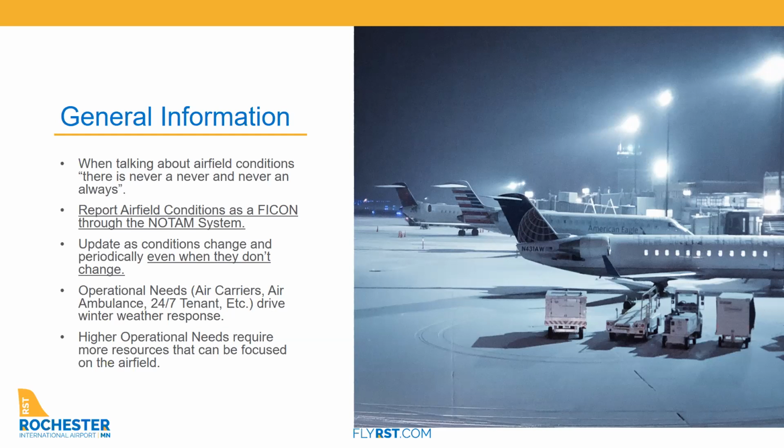So you have some generalities that you can follow, but it's hard to have a specific recipe for each and every time. And probably the most important thing that you can take out of this session today is to make sure that you're reporting the runway conditions at your airport as a FICON through the NOTAM system. Whether you're calling that in or doing it through NOTAM Manager, extremely important. And update your conditions as they change and periodically, even when they don't change.